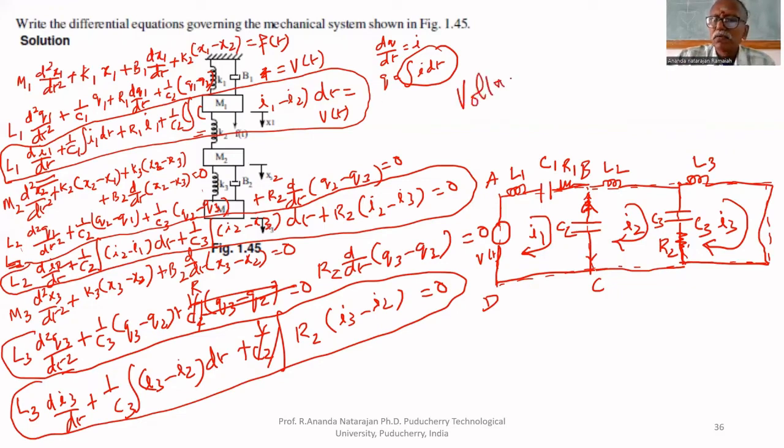Voltage analogy. Force voltage analogy. We can say force voltage analogy because force is analogous to voltage. Therefore, force voltage analogy. In the same way, we can obtain force current analogy. That is also possible.